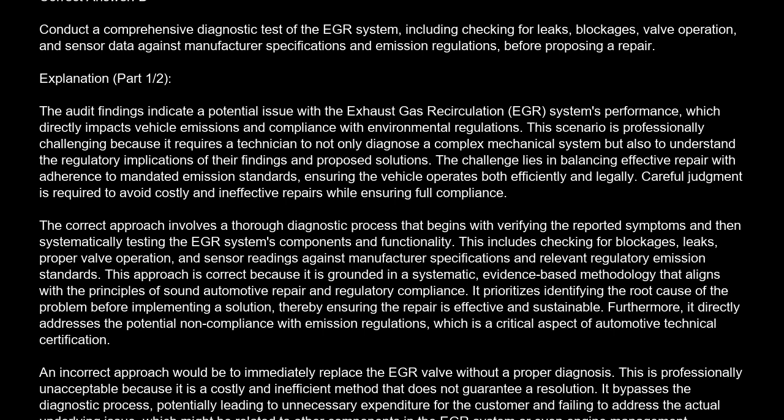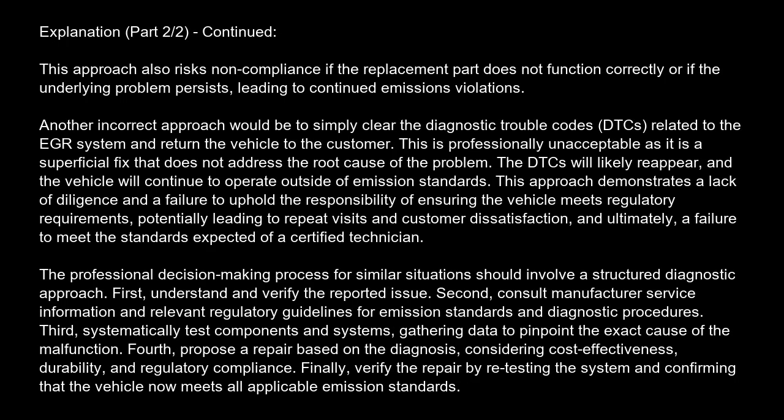It bypasses the diagnostic process, potentially leading to unnecessary expenditure for the customer and failing to address the actual underlying issue, which might be related to other components in the EGR system or even engine management. This approach also risks noncompliance if the replacement part does not function correctly or if the underlying problem persists, leading to continued emissions violations. Another incorrect approach would be to simply clear the diagnostic trouble codes (DTC) related to the EGR system and return the vehicle to the customer.